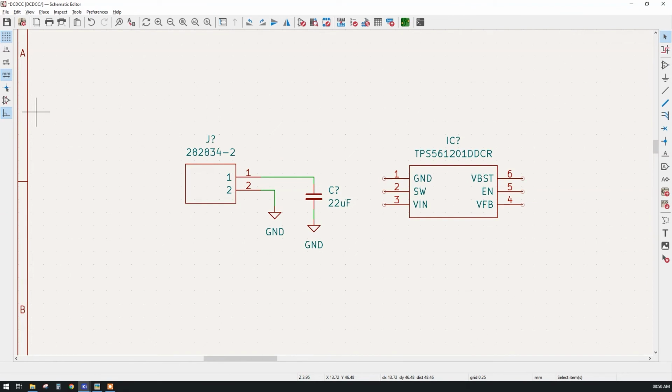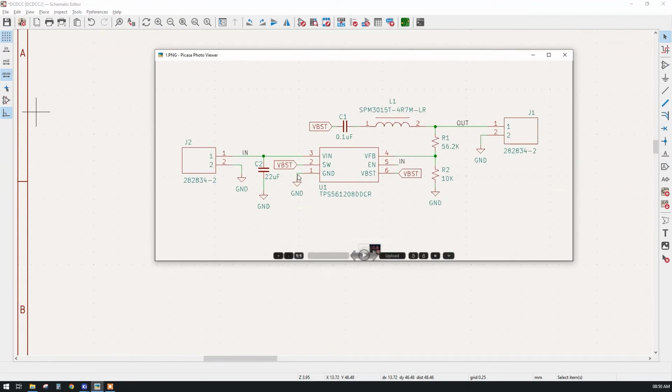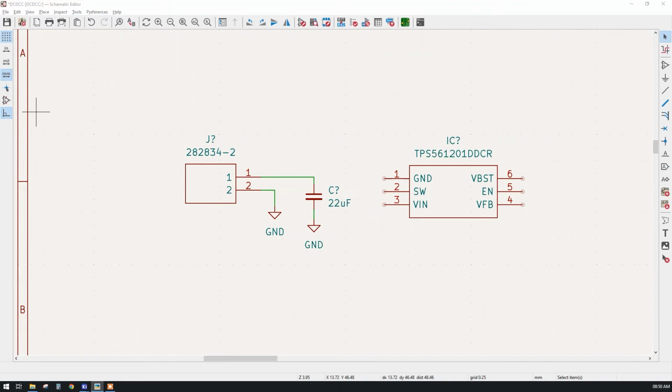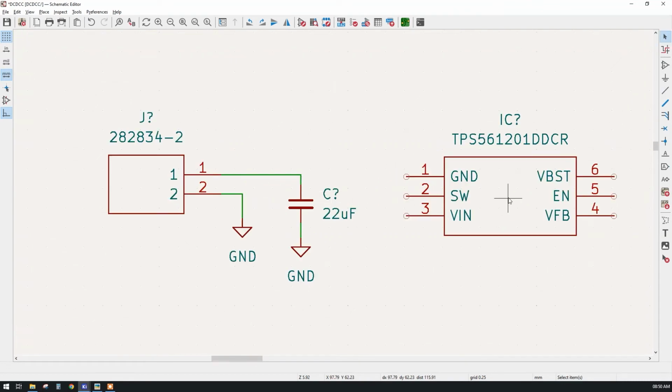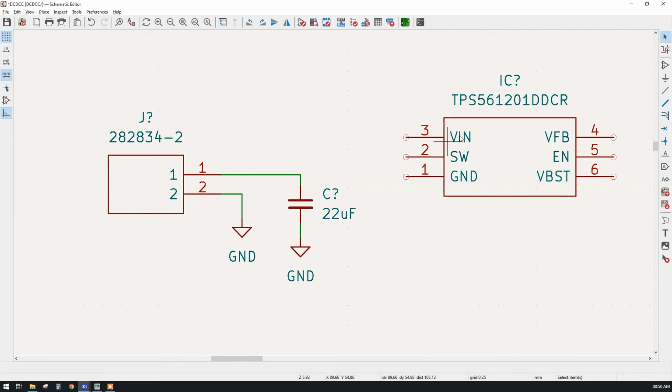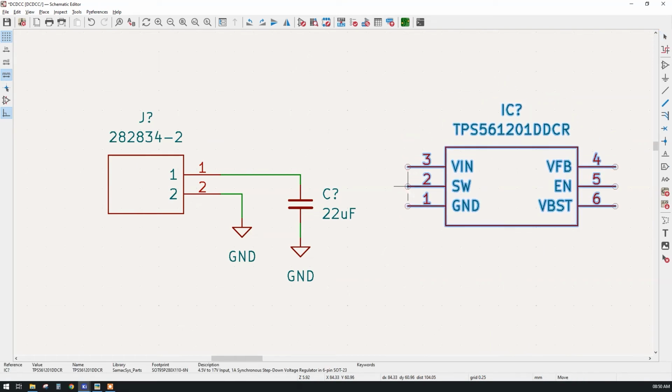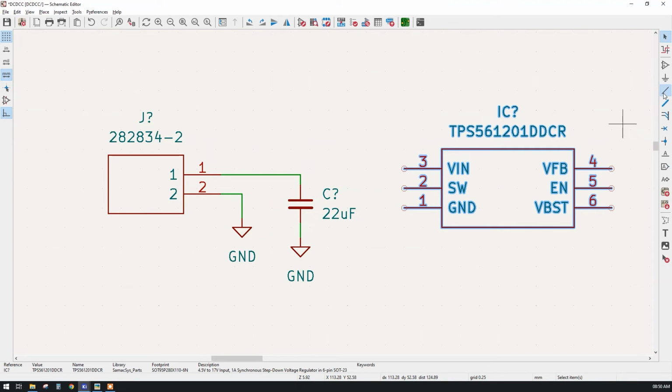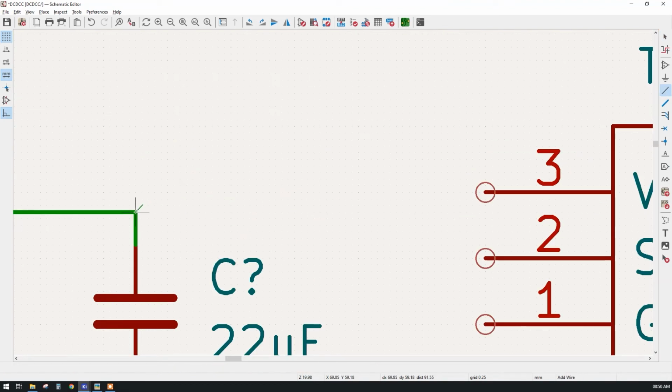Okay, see this, instead of nets we can use labels, or we can also use net names. Okay, so I will explain everything so that you will have a better idea of how to use the net names and how to use the labels. Okay, now we want to connect this line with pin number 3. So first I want this pin on the top side, so I will move it vertically. It will vertically move the entire symbol and it will be the mirror one. Okay, now to join this connection, I will start from here and I will extend this line.